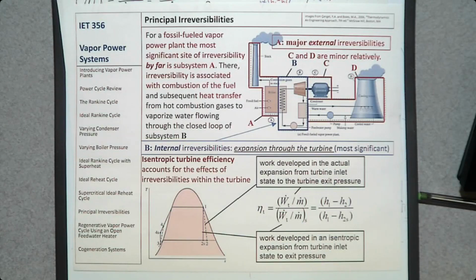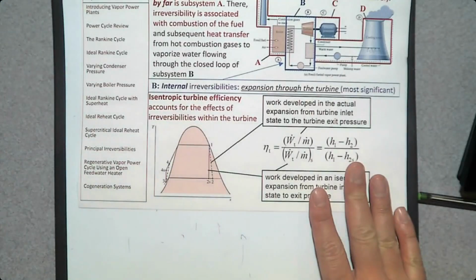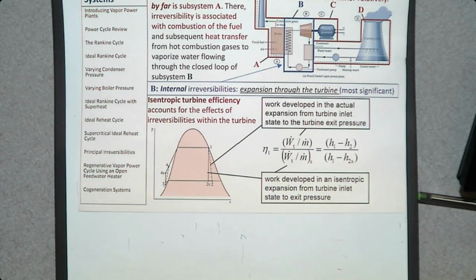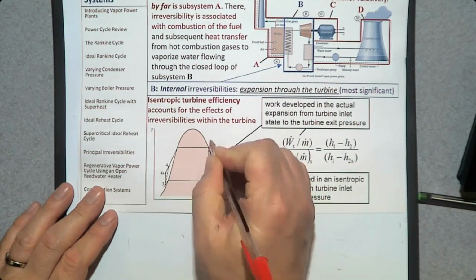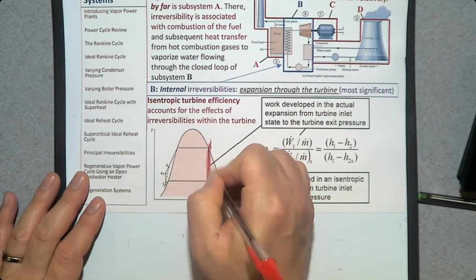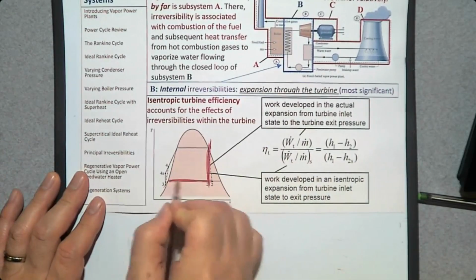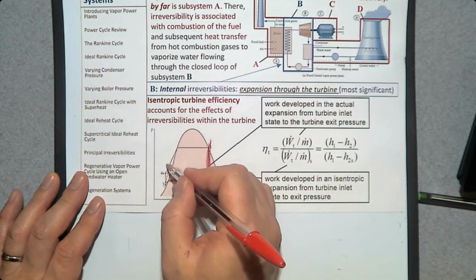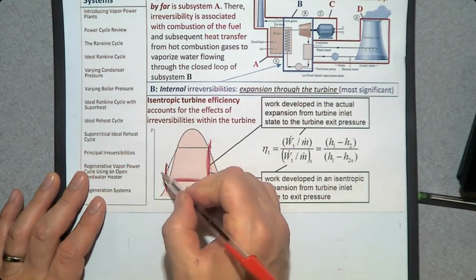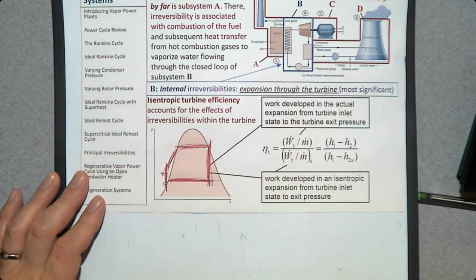Then, in this Rankine cycle, what is the main issue? Boiler, turbine, condenser, pump. The main irreversibility comes from the turbine. So, in reality, the ideal Rankine cycle has a vertical line for the isentropic turbine, constant pressure condenser, isentropic pump, constant pressure boiler, but in reality,